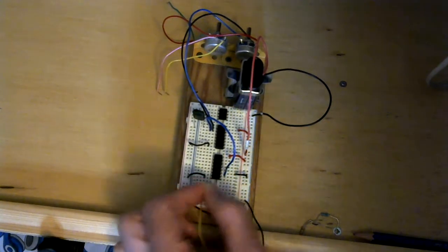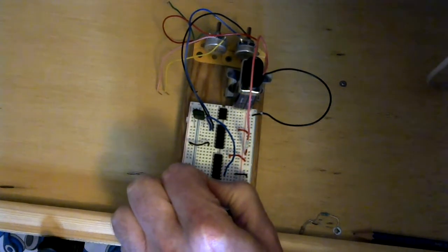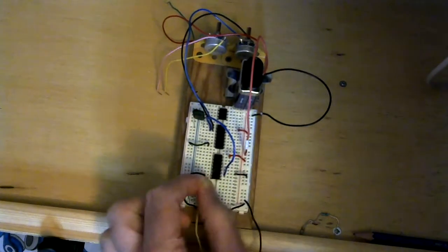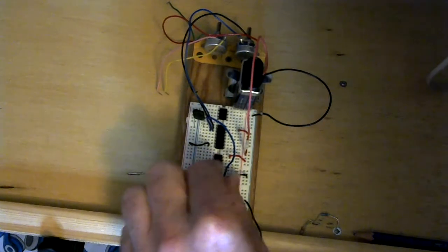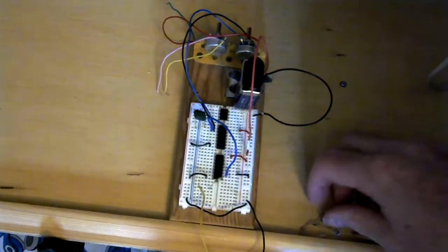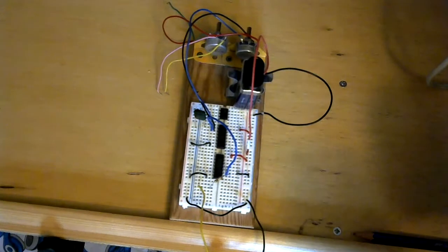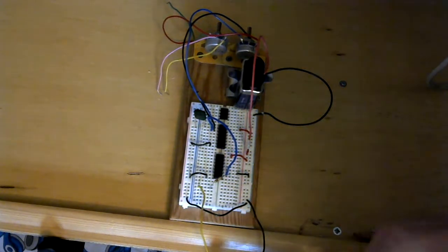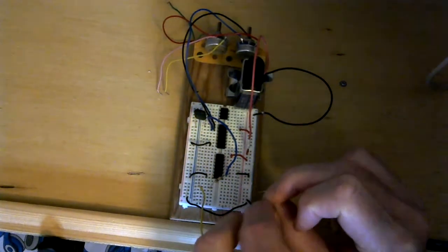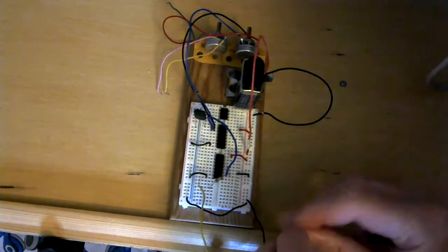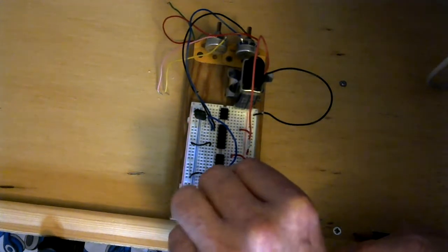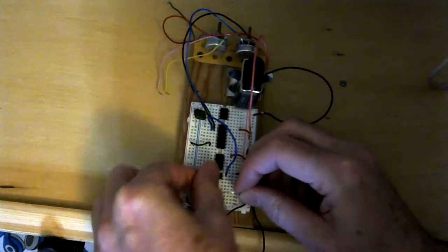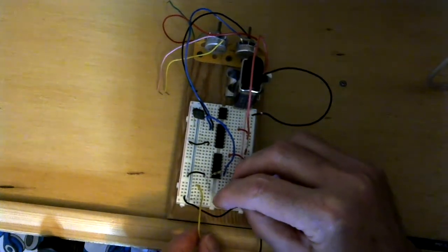First division 1 octave, next division 2 octaves, 3 octaves, and so on. Okay. But what we can do, and this is why I'm using a resistor, so that we stop them interfering with each other, what I can do is I can leave the output from the oscillator, but then take the output from the first division on the binary counter and put that onto the output.